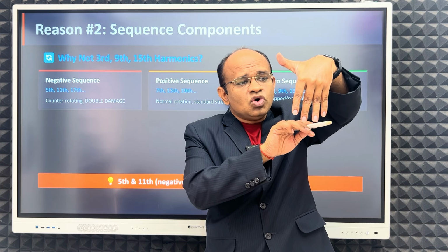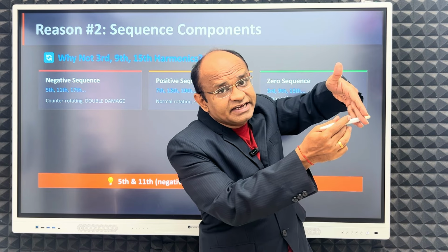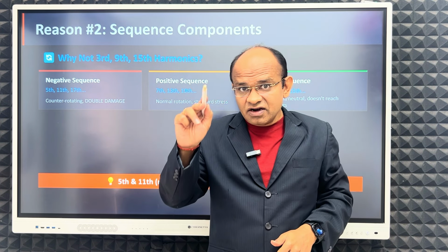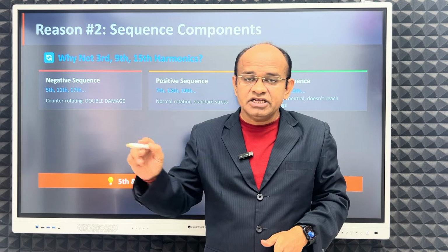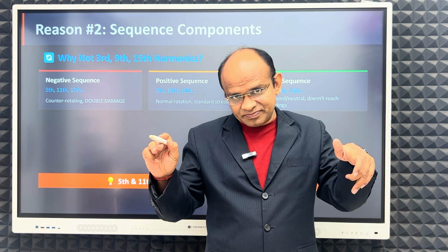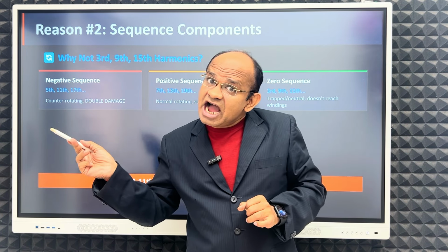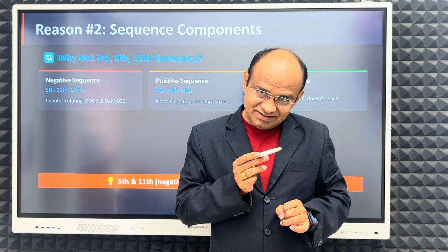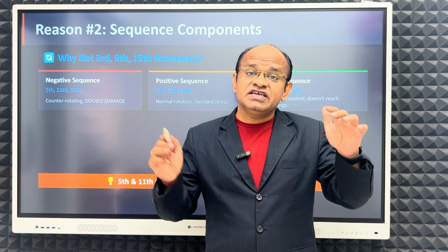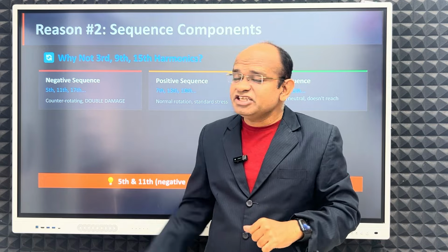When it cuts at 90 degrees, that is the peak, so our sinusoidal wave. Now the wave is moving in this direction, while harmonics are flowing in the opposite direction: negative sequence. If the sequence is exactly negative, it will do more damage.